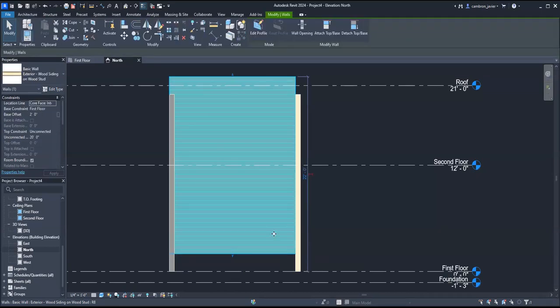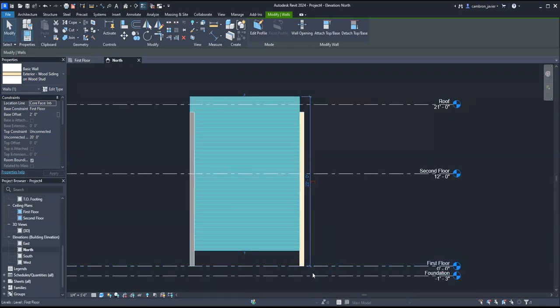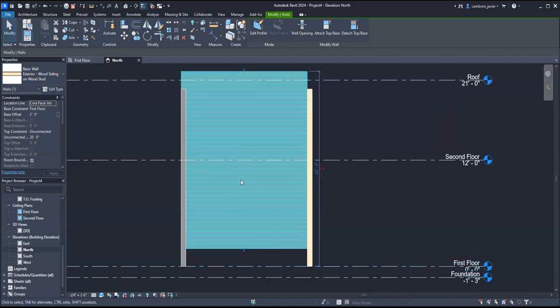Why is this important? When would you ever offset a floor? Well, if we have a raised foundation, or stairs, or if you're working on a hillside and your first floor has one wall that is hitting the hillside, we might construct that maybe 3 feet higher than the rest of the walls because that's where the topography is. So we have that option of offsetting the wall from the finished floor. This way we keep everything attached to the first floor, but maybe that one wall is different, so we don't have to create a new level line for that.